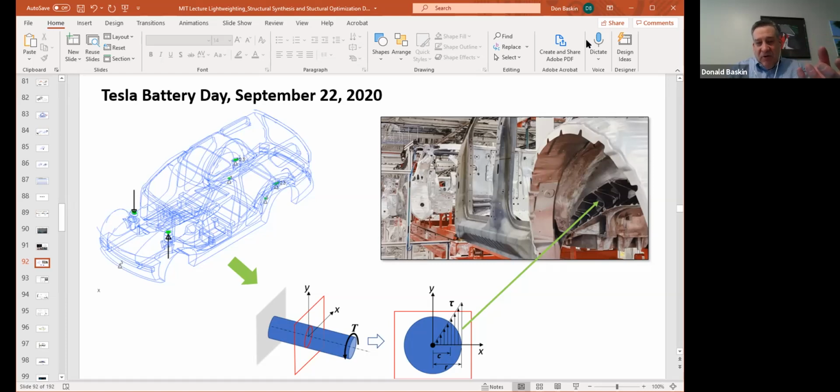One, to hold the jelly roll of lithium alloy and graphite, the anode and cathode, and then also use it to separate the structural panels of the bottom of the car. So effectively what you're doing is making a honeycomb sandwich, but you're using the battery structure twice. You're using the can twice: one, like I said, to house the jelly roll, and the other to separate the floorboards.